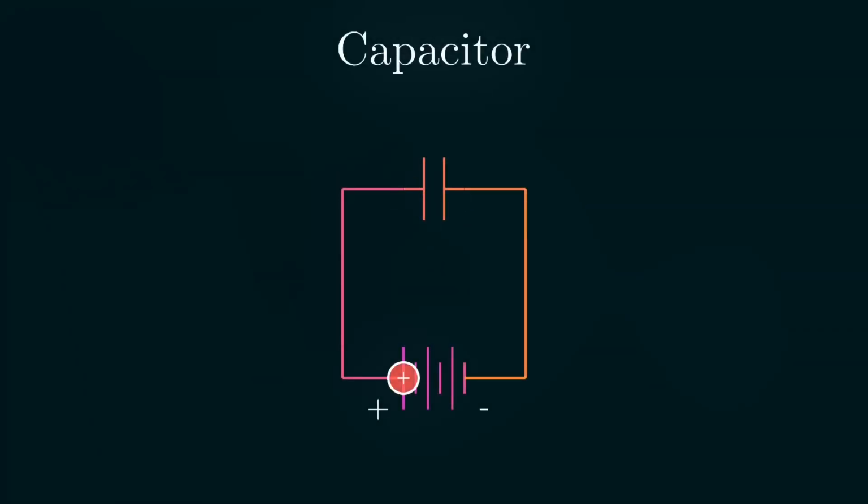And if you put it across a voltage source, then the charges are going to flow to the sheets since they're attracted to the other side. But when they reach the sheets, the same sign charges on the opposite side are repelled, so they basically continue across the circuit, although it's not exactly the same charge. However, now there's more positive charge on one sheet and negative on the other sheet, which means that over time, the capacitor will eventually reach equilibrium when it has a voltage across the plates that's directly opposing the voltage created by the battery.